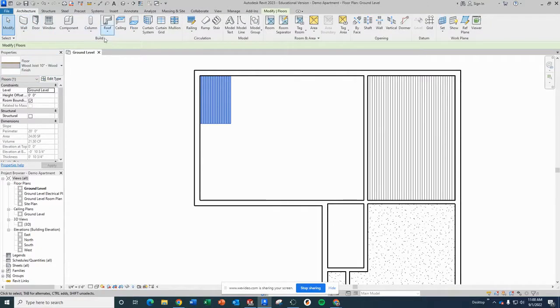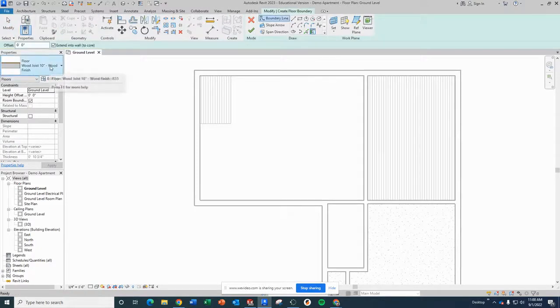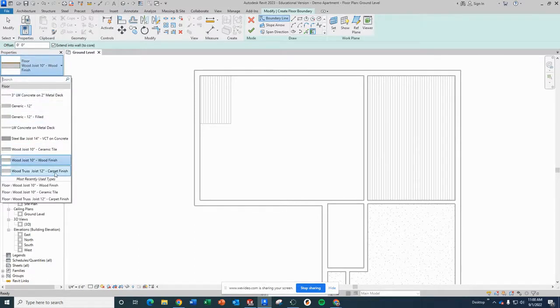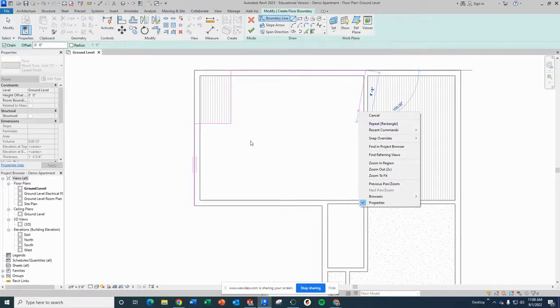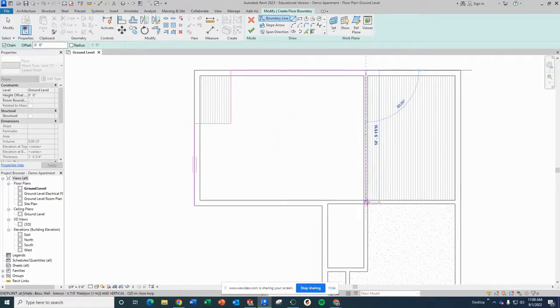as guides. So as I add a floor, I am going to switch to the carpet finish. I am going to grab my line tool and I'm going to start just on a corner here. I'm going to come up and find the endpoint, find the endpoint, find the endpoint there, all the way across to the endpoint here, down along to the endpoint here, across to my endpoint there, down to the end of this line, and across.